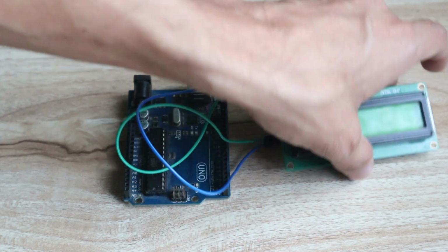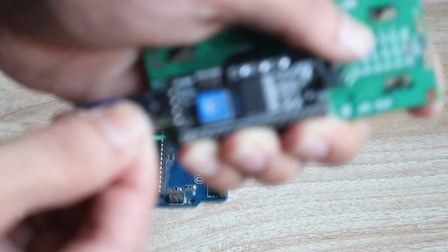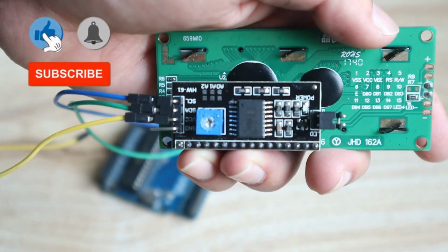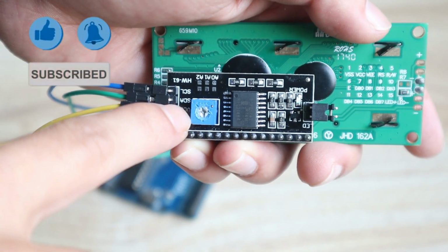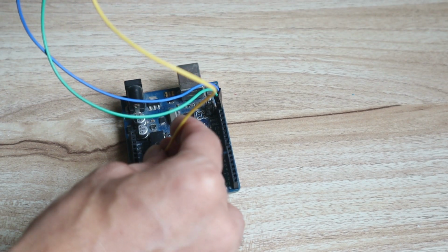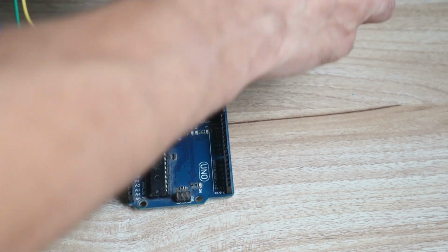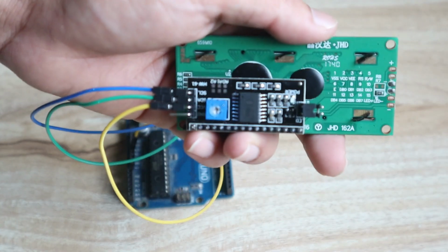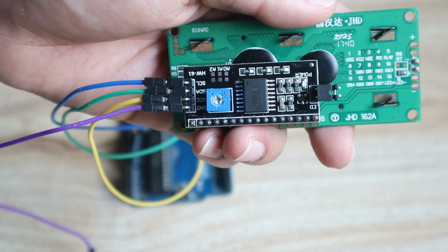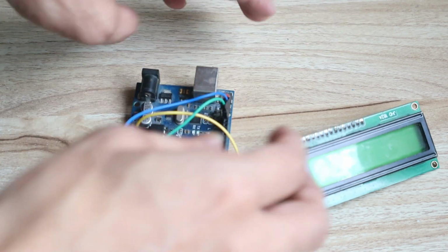Now VCC and ground. Take the VCC pin from the I2C module. You can see here I have connected the VCC pin to the Arduino 5V pin, easily available on the Arduino board. Just connect it to the 5V pin here. And the same here, this is the ground pin from the I2C module. You can see I have connected the ground pin. Just connect it to the ground pin of the Arduino. That's it, the simple connection.